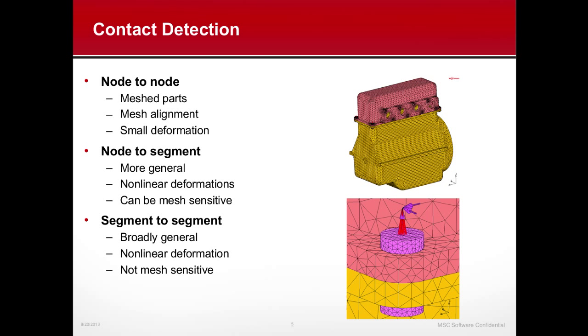And so in nonlinear analysis, the node-to-segment approach has been very popular and used by most nonlinear solvers. And in this approach, contact between a node with a segment is checked. And some of you, if you're familiar with the master-slave approach, this is the method that is generally used. And since the segment can be either a geometry or an element face or an edge, this provides a much more general method to address the contact problems.